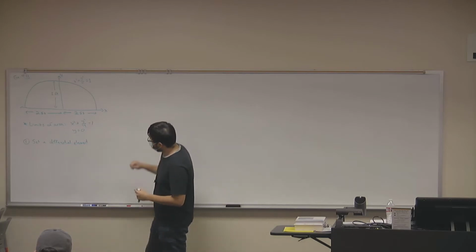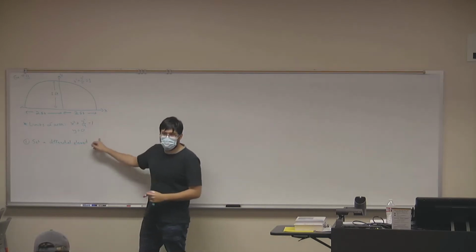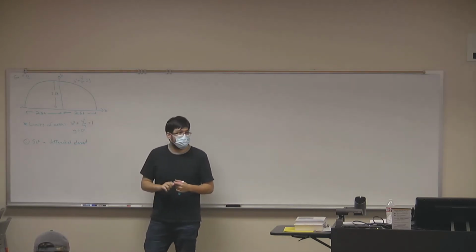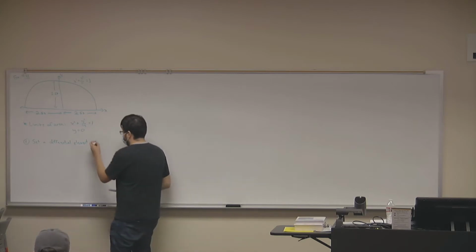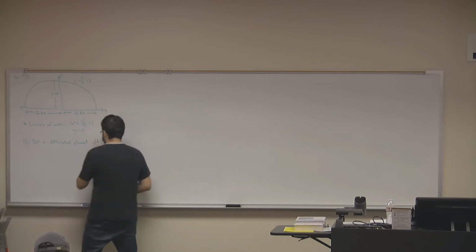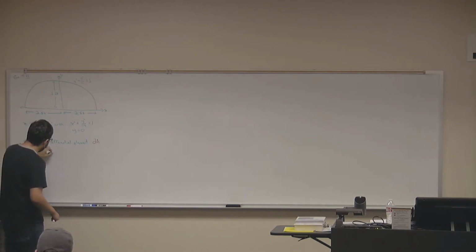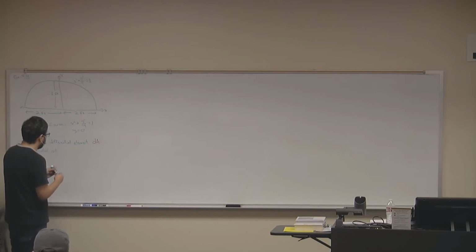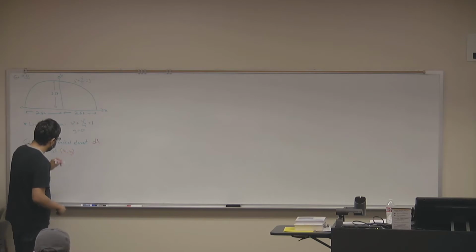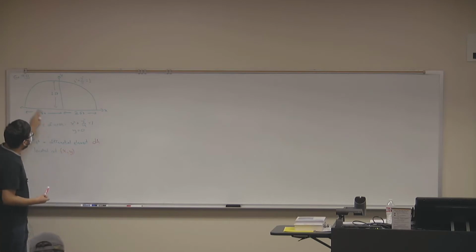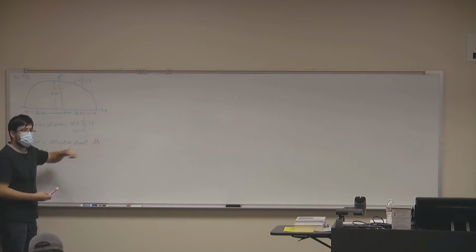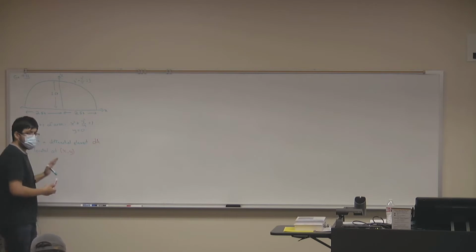But in 2 dimensions, that differential element would have what type of dimensions? dA, right? So we're going to set a differential element dA that is located at some arbitrary point, which I'm going to call xy. Okay? And this will be an arbitrary point in my curve, because we know that to find centroids, we integrate.